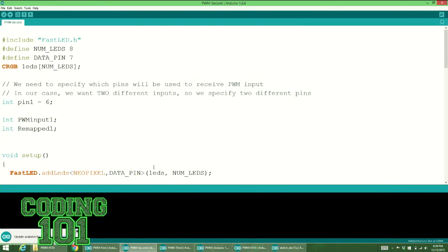which looks like this. So I've already done a little work here. If you've watched the previous episodes of our Arduino work, you know the FastLED library. This is a library that gives us control over WS2812 lights, among others. There are a couple of other pieces here that you need to know. Define the number of LEDs. This allows me to tell the Arduino, when it's dealing with the FastLED library, how many LEDs it will be addressing.